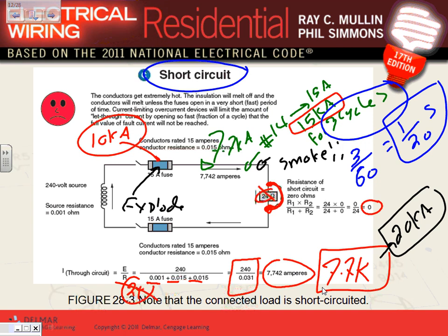If I have a ground fault, suppose that I have a green conductor coming from here. Here's my ground, and here's my conductor coming all the way to tie to the equipment, right? And then my troublesome friend Dustin this time went and grabbed the hot and tied it to the ground conductor or the neutral conductor. Any grounded conductor, could be an equipment grounded conductor or a grounded conductor, the neutral. Tie them together. That's your ground fault.